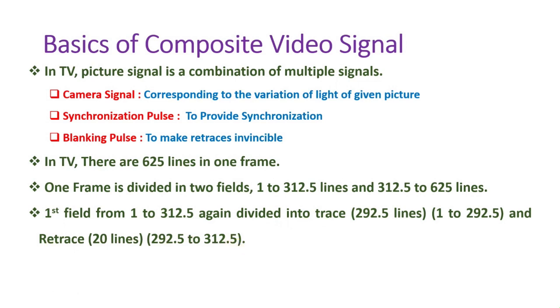Video with negative alignment polarity is required on the control grid of the picture tube to reproduce the image. Then the blanking level is negative to cut off beam current for black. Video with positive alignment polarity is required at the picture tube cathode. In addition, negative alignment polarity is the standard for internal or external signals from video equipment such as television cameras, video control equipment and distribution networks. The standard amplitude is 1 VPP with negative sync.